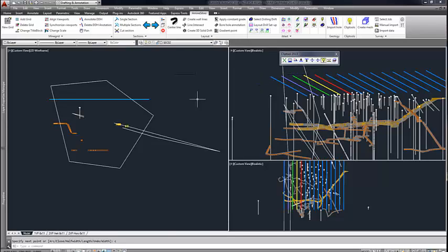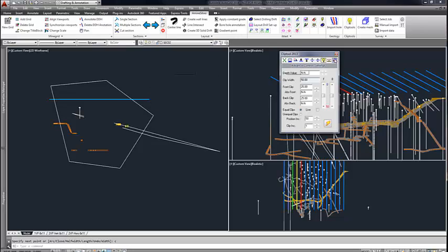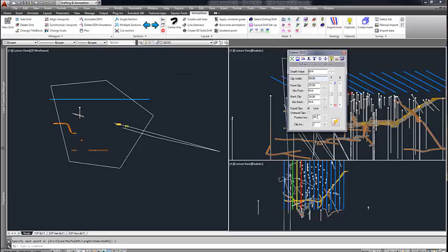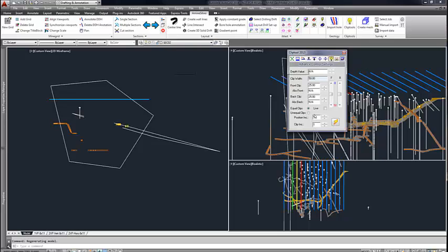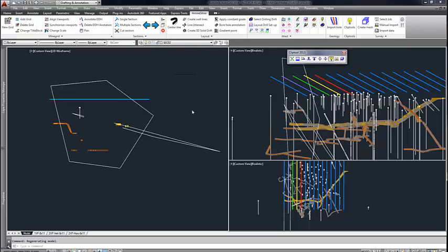Now I want to step through these sections quickly. So I know the sections are 50 units apart, in this case 50 feet. So I want to set my value down in a position increment and set that to 50. I set it to 50 and I hit the lightning bolt. What that does is whenever I use these 2 arrows here, it will step forward or backward from the screen in the view I'm in by the unit that was set in this position increment, in this case 50.